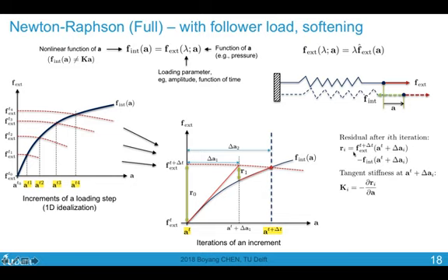Previously, we did not have the contribution from external force. Now we have it, and it's called the force stiffness, or the load stiffness. So now this line here is only representing the contribution from the internal force. So it's not the true representation of the tangent stiffness Ki. And then we do the same to update the displacement correction. So you see that this is not an exact expression of what's happening.